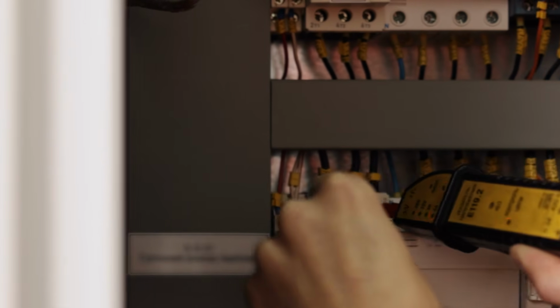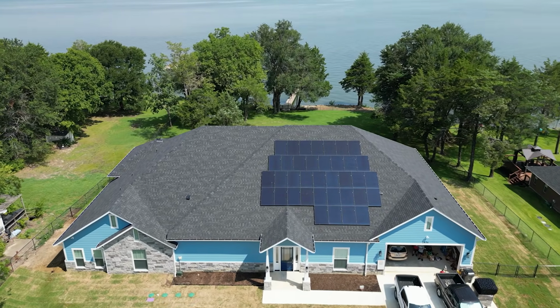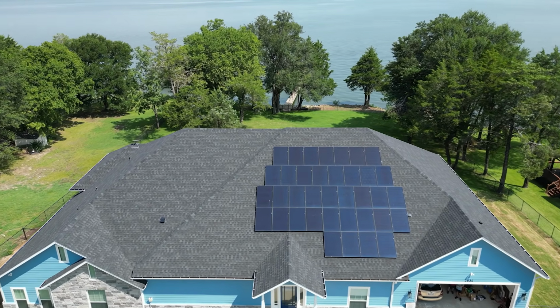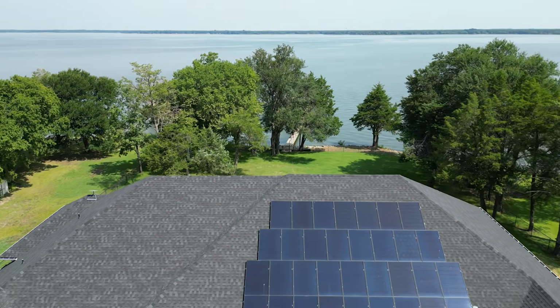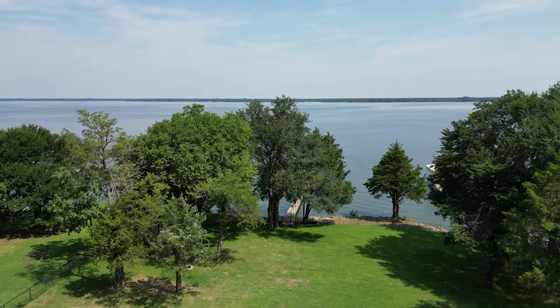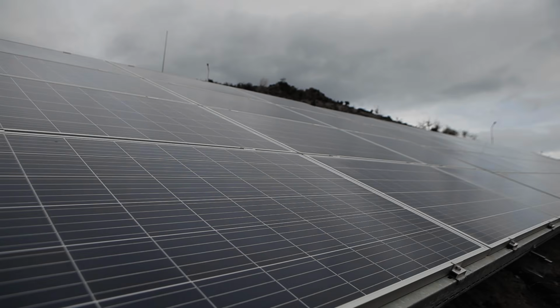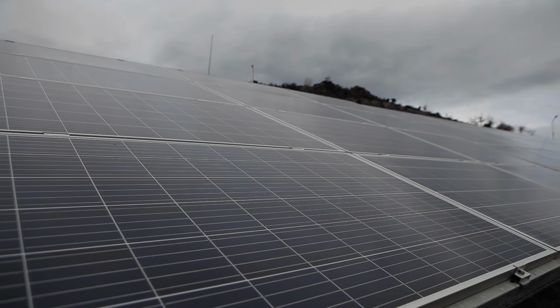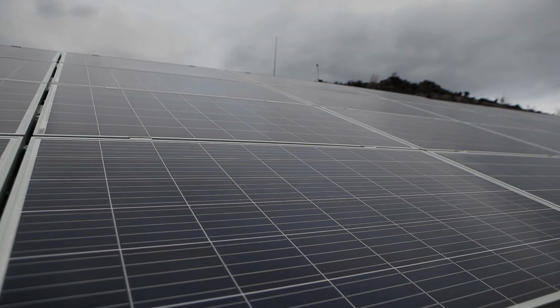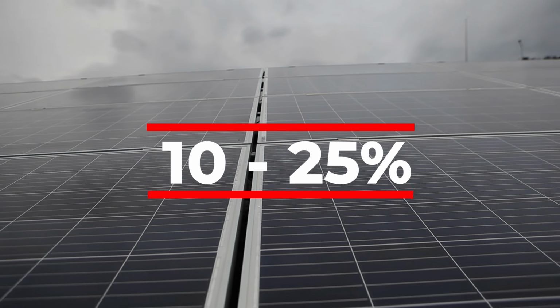It's very important to understand that a 5 kilowatt system doesn't always produce 5 kilowatt hours every hour. Several factors affect how much energy your panels actually generate, and I think this is where a lot of people get confused and dissatisfied with their systems. So first, there's panel efficiency and temperature coefficient of the panel. Then there's also weather, clear skies, more clouds during the day, or cloudy and rainy days. Your panels might only produce 10 to 25% of their rated capacity.